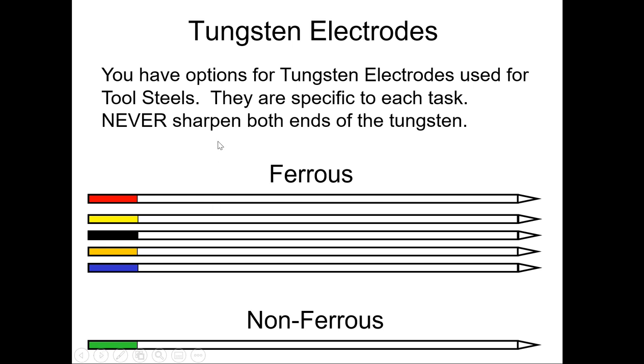Different types of tungstens. Your tungsten you're going to be using, there's a couple of different options actually. Now, this is your pretty standard 2% thoriated. There's 1% thoriated. There's lanthanated. And then we have ceriated and lanthanated. Ceriated is the blue, and these two are actually known, I've seen these two packaged as lanthanated. Now, these are used for basic ferrous materials on standard equipment.